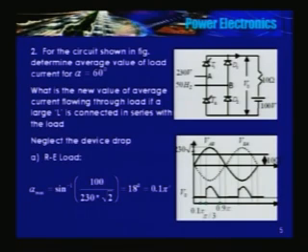So Vi minus E is nothing but I into R, so I has to be 0. So current becomes 0 at 0.9 pi. Thyristors T1 and D2 turn off at 0.9 pi, and from 0.9 pi till you trigger the next pair, that's only at pi plus alpha, that is at 240 degrees, current flowing in the load is 0.